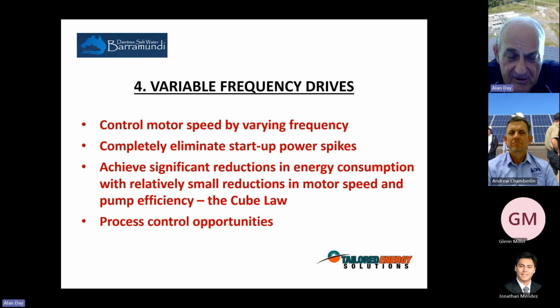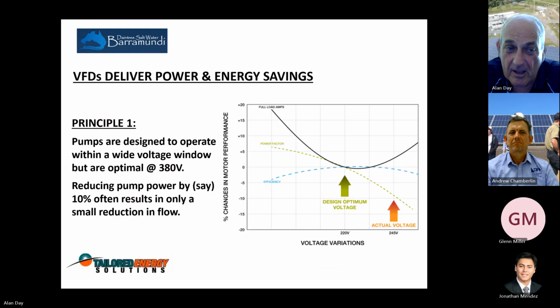But as I said, very often these days we're just using a VFD or a VSD as a very fancy soft starter. A lot of people just whack in a VSD and reduce the frequency to 90% and walk away with the gains. One of the reasons I say that here is if you look at just the second point, reducing the pumping power just by a small amount seems to have not very much effect on the volume of flow. That's just something that people have observed.